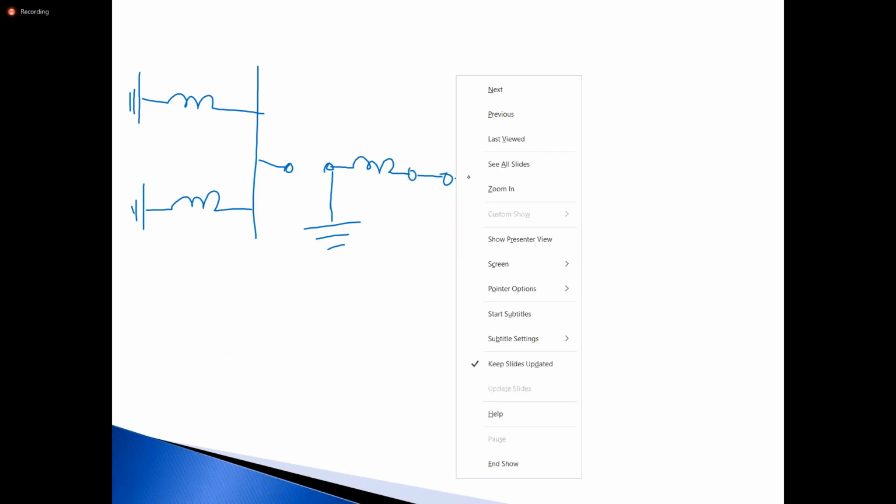All right. So because you have the delta, you have no zero sequence. So we have open A and we have closed B. And then you have the reactance for the transformer. On the other side, for the grounded star side, zero sequence will flow. So since zero sequence will flow, you close A and open B. What does that look like? We have closed A and B open. We don't have to worry about it.